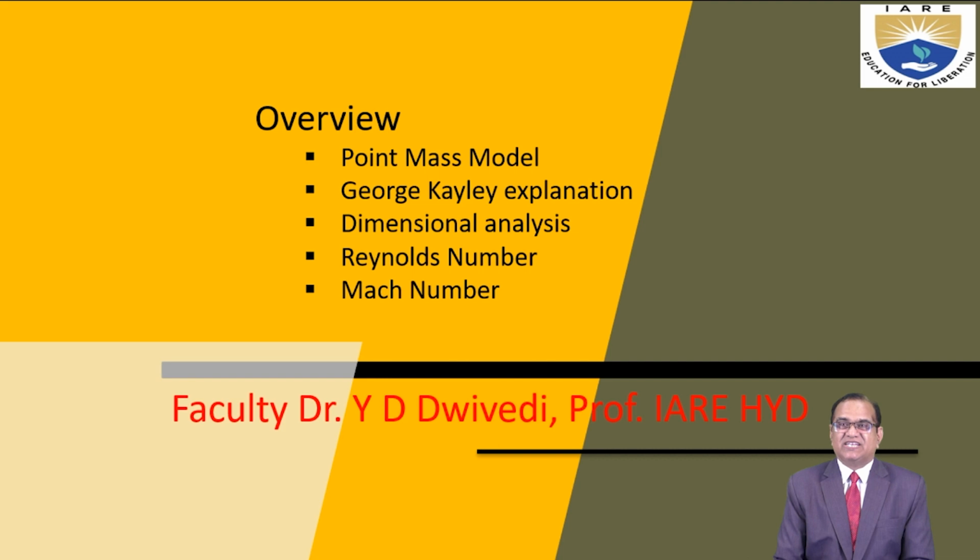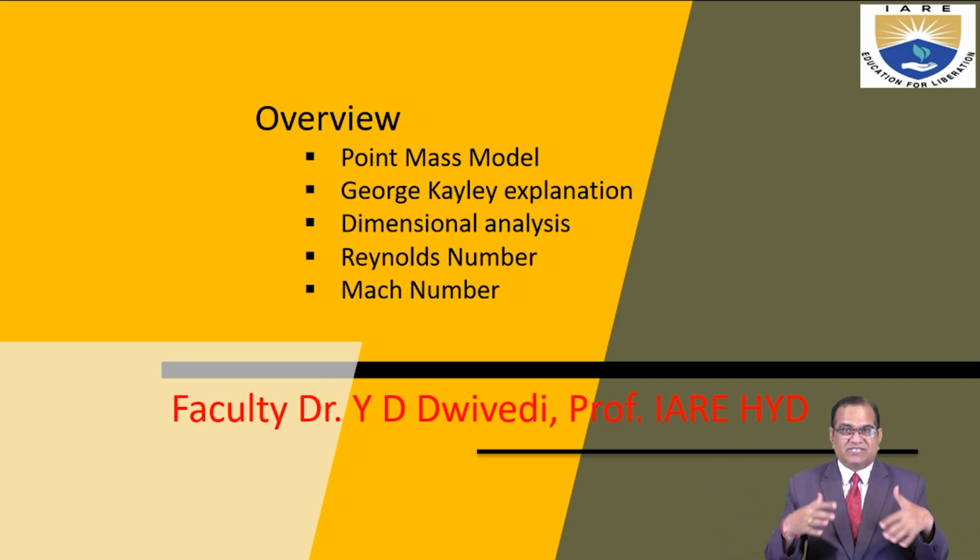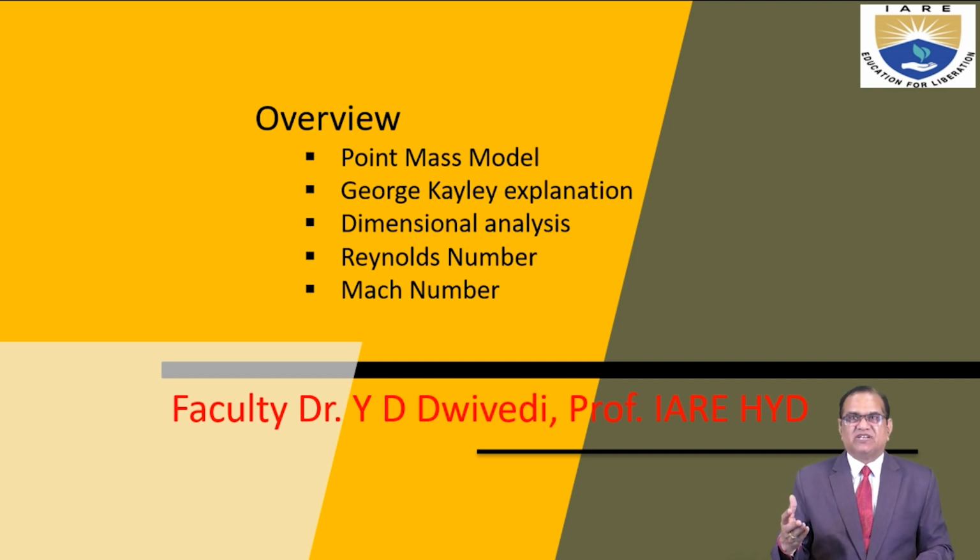If you do wind tunnel testing or computational fluid dynamics, you have to understand that if you have a very big aircraft, you cannot test it inside the wind tunnel. You need some method. So dimensional analysis makes some non-dimensionalization of numbers, and those numbers are very useful in aeronautics. Two numbers are very important, the Reynolds number and the Mach number. We will discuss this today, and we will also see the point mass and the George Cayley explanation for the lift.